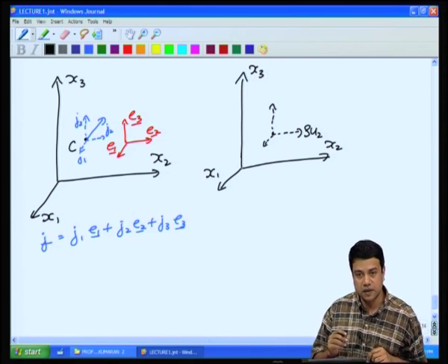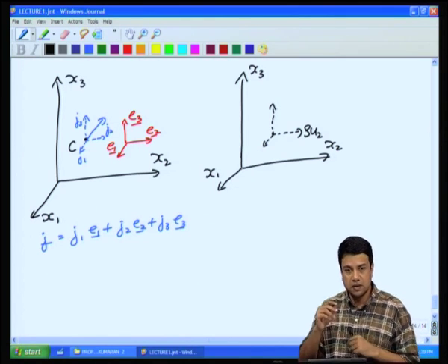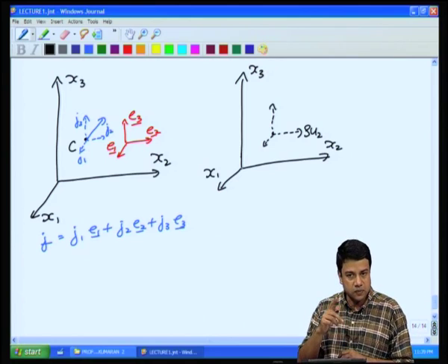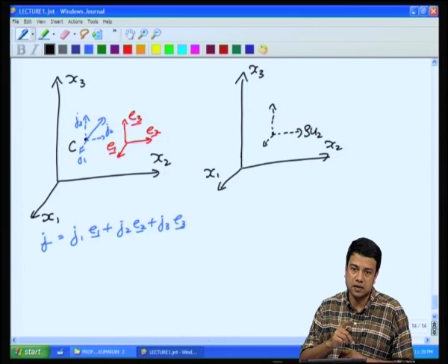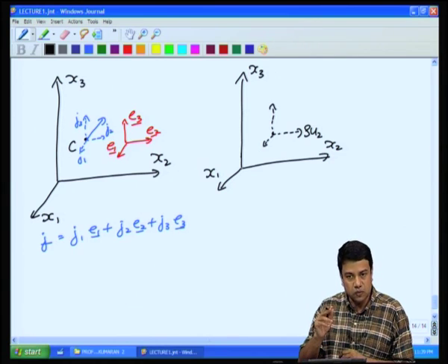So, therefore, you have an object which has 9 components. In the case of momentum, you have two fundamental directions. One is the direction of the momentum itself, because momentum is a vector. The second is the direction of transport. That is, the direction of transport of momentum basically results in a force acting on some differential volume.